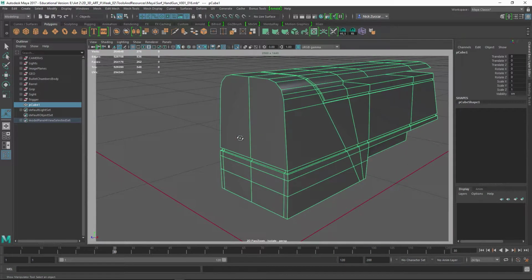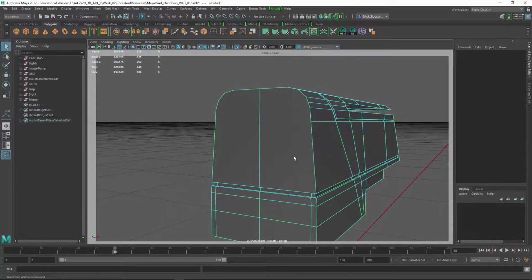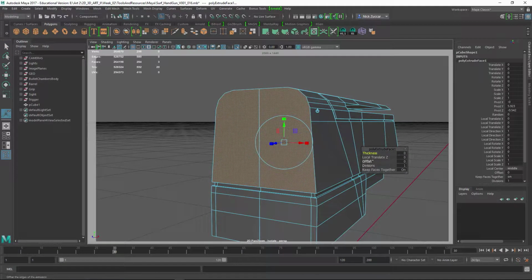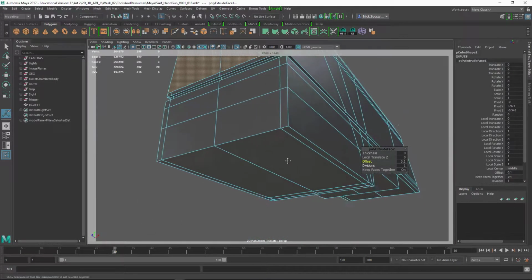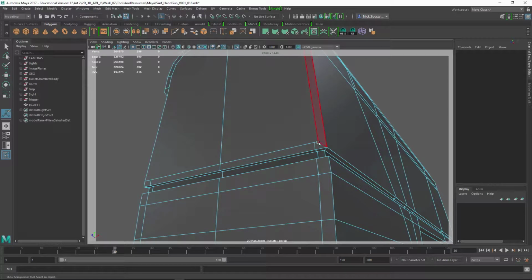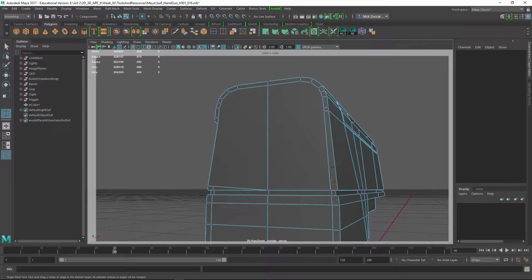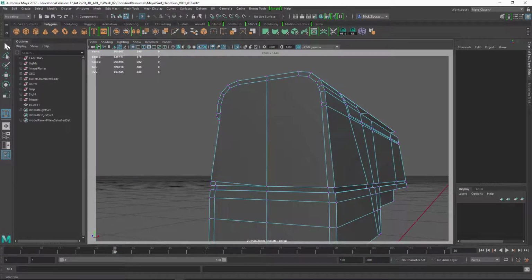I do know if we wanted to continue this line going up and through here, what we could potentially do is something like this. Shift right click, do extrude face, and do an offset. I want something that's kind of like this, but just to get this part that I want right here, but I don't want these verts here. So let's go F9, shift right click, merge vertices, target weld. Let's weld this. We got that, and then we'll weld that there. And that way I didn't have to manually cut all that geometry going across and everything.